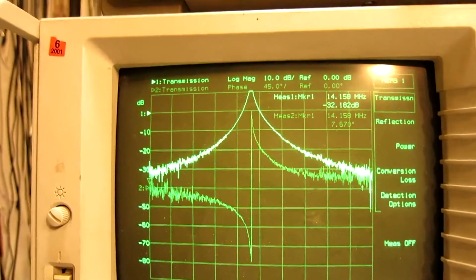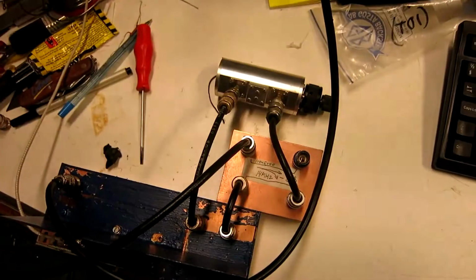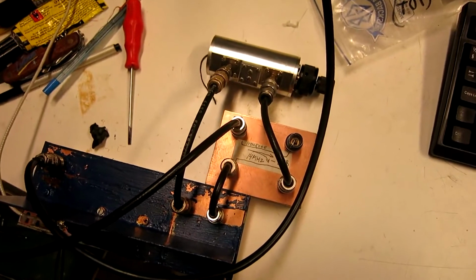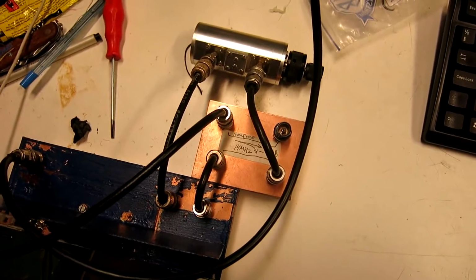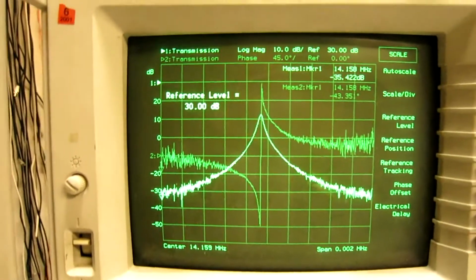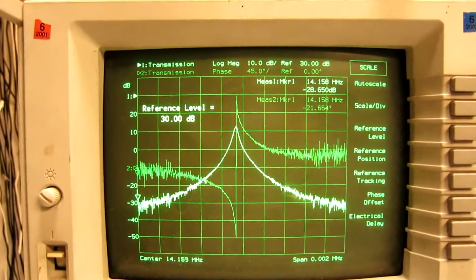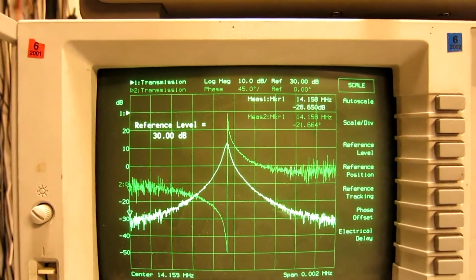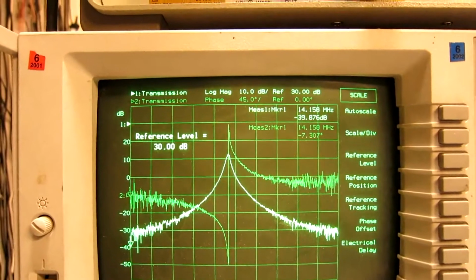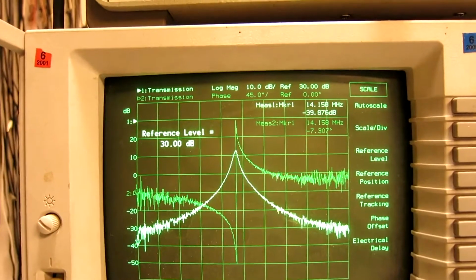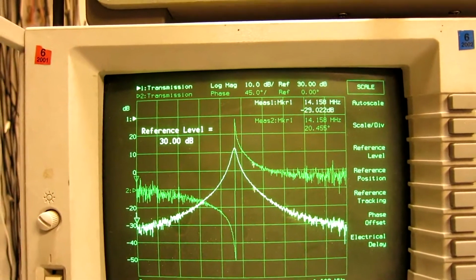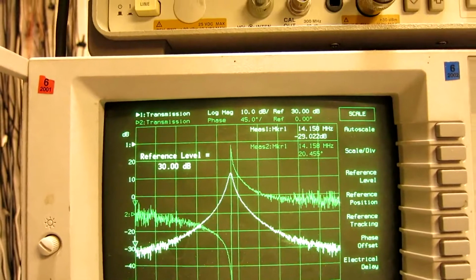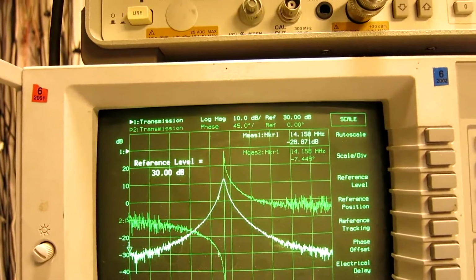I have to rearrange things a little bit. So I removed one of the attenuators, and there is now 5 decibels in the remaining attenuator. And this is what the network analyzer shows. The gain has increased from 0 to 13. Remember, there is another 20 dB in the directional coupler. The sweep speed starts to be a bit high for this very narrow peak.